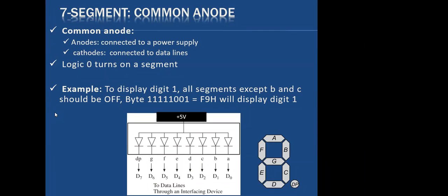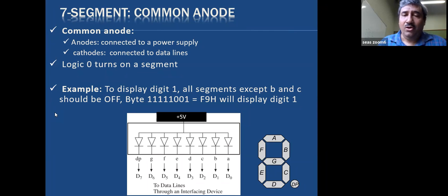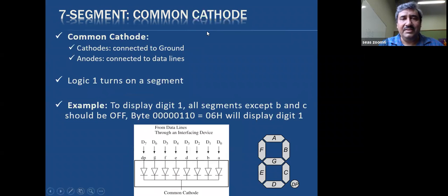And now remember that there is no 1-to-1 match. If you write 01 hex, that will not turn on 1 when we display it. When we say 02 hex, it is not going to turn on 2 on the display, right? So there is no direct match. We need to make sure that we have the right combination of bits to turn on things.